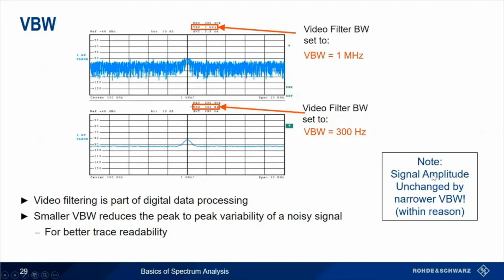And the last thing to keep in mind is that the signal amplitude is unchanged by the narrower video bandwidth. I think of it as cleaning up the display, versus resolution bandwidth, which is actually changing the way that we are capturing the information itself.